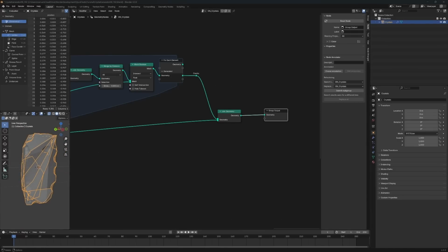But there's one more thing that we have to deal with, and that is that we want to flip the faces of all the internal pieces again, because remember we want to give it a transparent shader. That means a ray of light is hitting the surface, that it's entering the volume, and then it's hitting one of these cracks. So to the ray, it looks as if it is hitting a surface from the outside, yielding wrong results in the refraction.